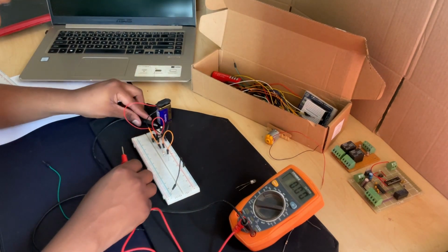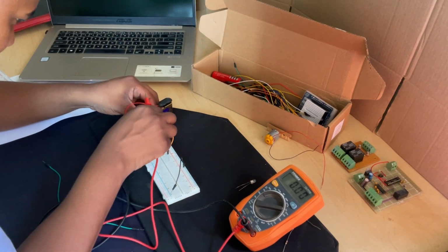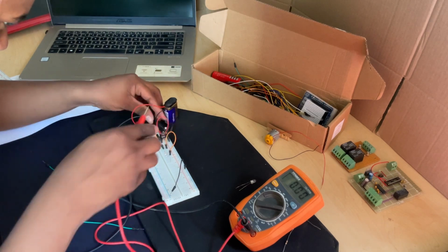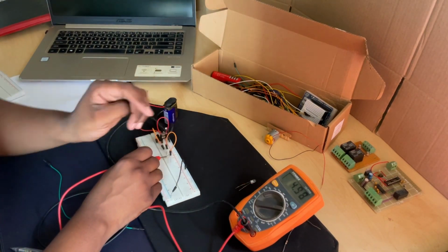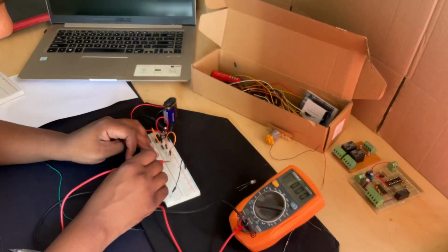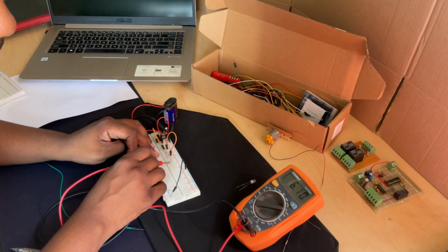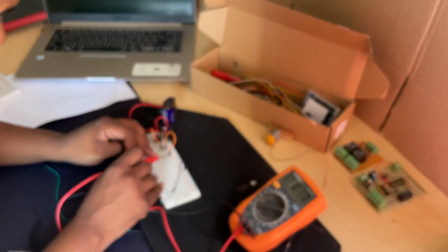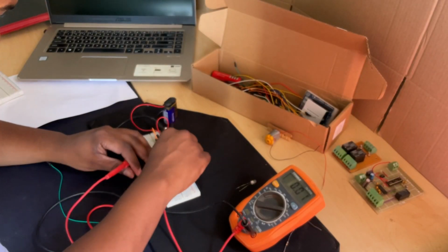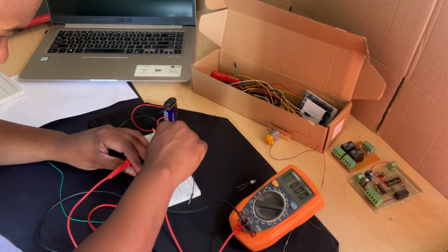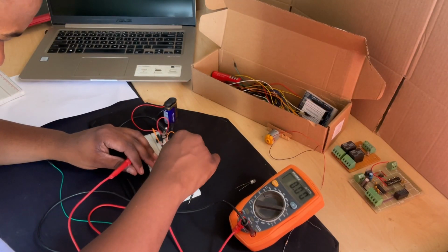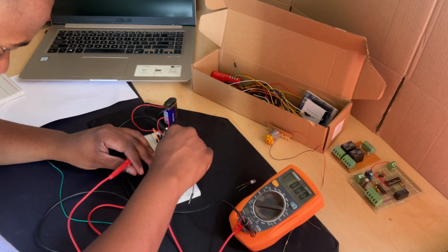We first start by building the circuit by placing the two resistors. Then we adjust the multimeter to be in voltage mode and make sure that our negative lead is connected before taking the measurement. And what we see here is part of troubleshooting where the value is higher than what is expected and a mistake was noticed and rectified.